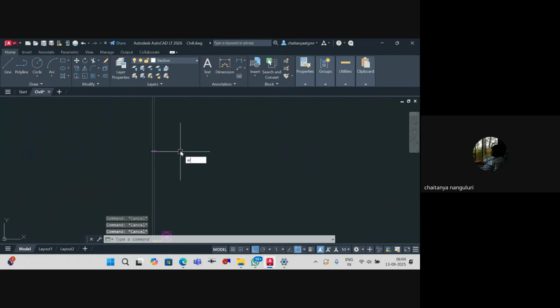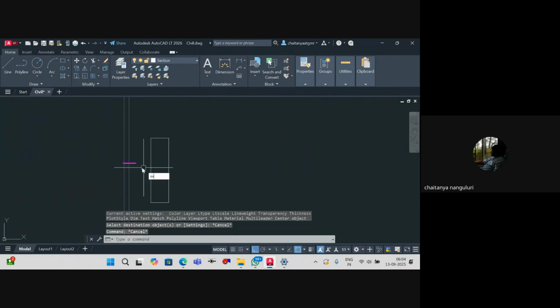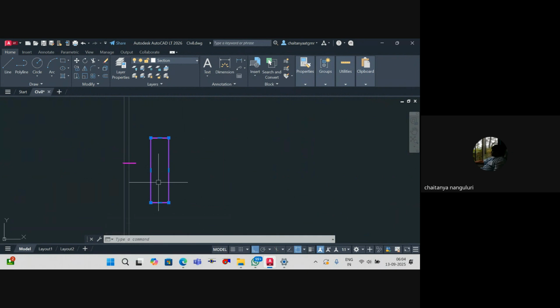So here I'll have my outdoor unit. Let's say this is my outdoor unit of 16.5. 16.5 means obviously I'll not have a single circuit, I'll have two circuits. Because for 16.5 tons you don't have a single compressor, you'll have two compressors. So probably one 11 TR and one 5.5 TR. Understood?